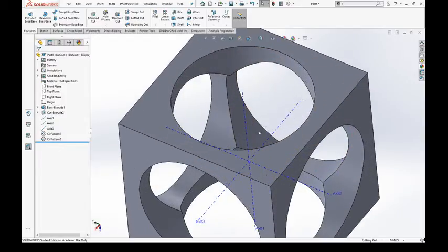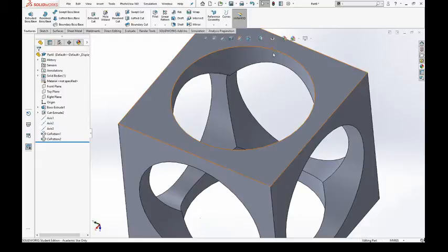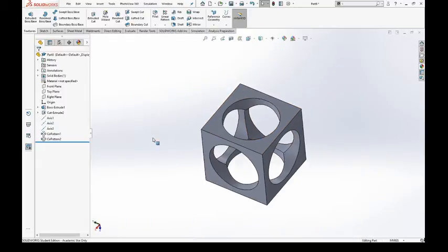Now, these are probably becoming a little bit in the way now, so we're going to remove these. So we've got a little eye tool up here. I'm going to just choose to turn off my view axis. Okay, and they just disappear. They're still over here. This is known as the feature manager. They're still over here, so I've still got all 3 of them there. However, because I've chosen to turn them off here, they disappear. It just makes things a little bit easier to see.